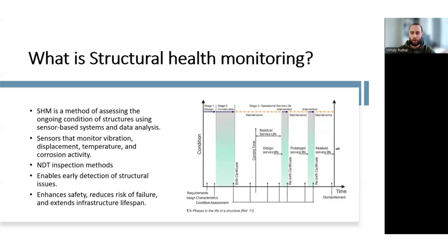In modern construction and high-value projects, structural health monitoring is becoming something that is planned for from the design stage, but you usually don't have that luxury with many existing buildings, especially as we have shifted towards a more reuse and recycling of existing structures as opposed to demolishing and building anew. To this extent, non-destructive methods help structural health monitoring and guide repair and refurbishment strategies.